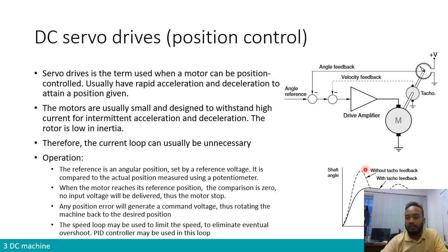If you have overshoot, therefore it has to go back to the opposite speed, and if it is too much speed, then it will go into the negative overshoot. Therefore, you will observe a certain oscillation, which is not desirable, right? So without the feedback and the velocity loop, without the feedback of the tachometer, you will observe an overshoot and oscillation response of the speed, like this, of the position. So it goes beyond the position that we want. So here is the position that we desire, it goes beyond, and then it has to go back and return again, so there will be an oscillation.